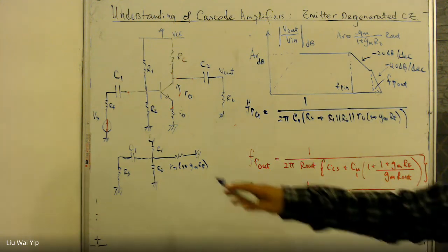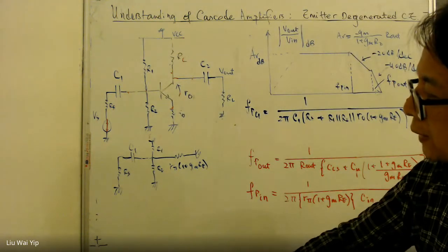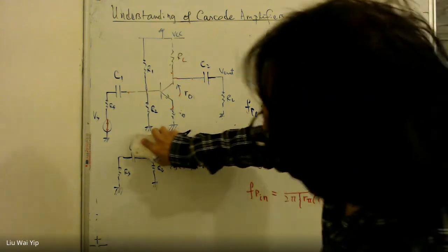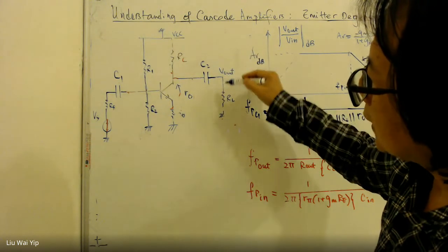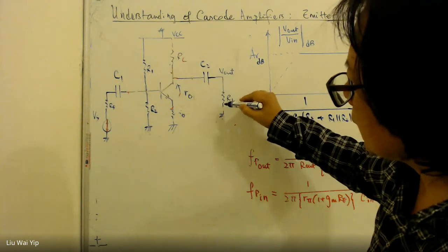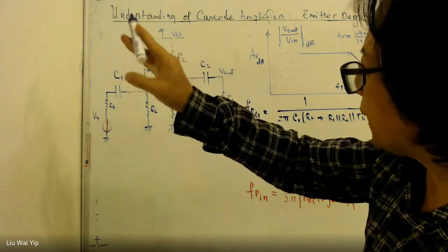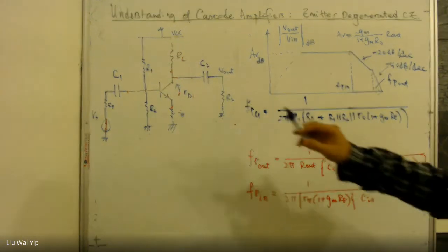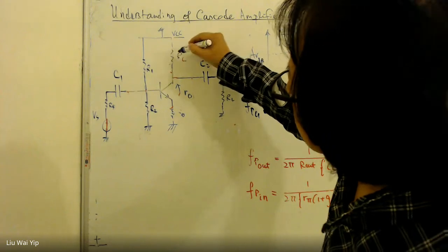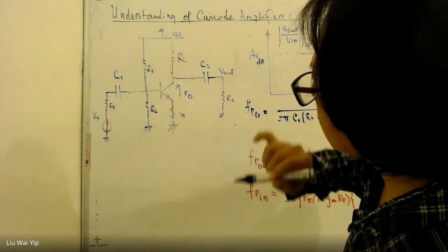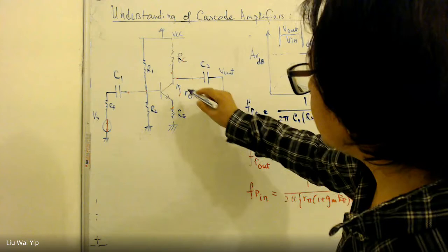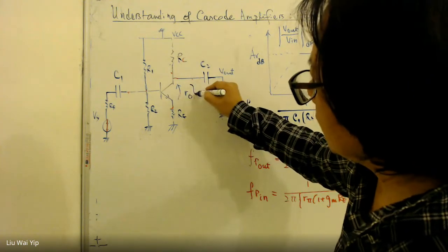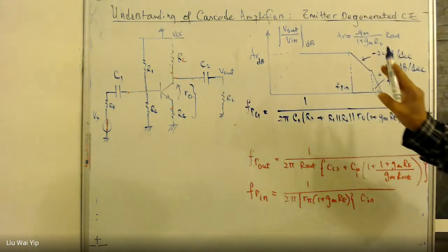And how about the one associated with the output here? Now I don't think you need this part, this circuit. And now we have C2 here. The right side of C2 is connected to RL. The left side is complicated. We have two resistances. One is RC, the other is RO times some resistance. And we know this from the small signal theory.